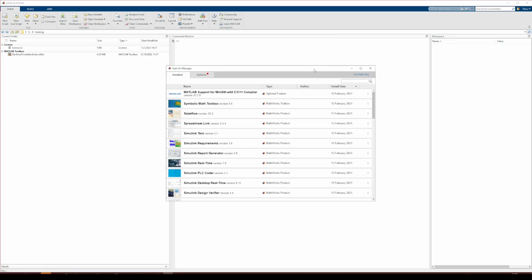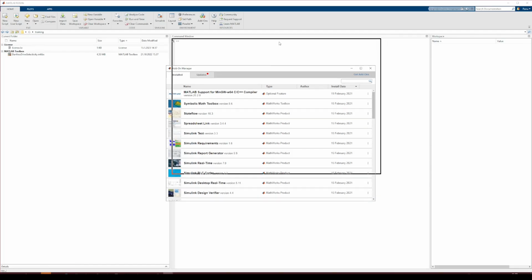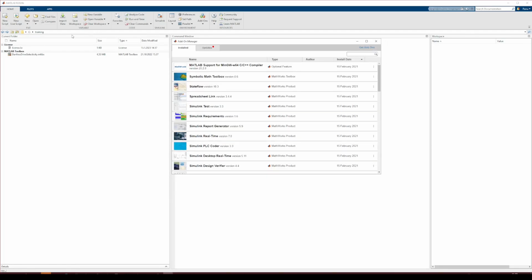If you want to carry out the uninstallation successfully, it is best to reboot MATLAB and then do the uninstallation to ensure that all the files and folders are removed successfully. And sometimes there may be a conflict if you have some files open from the installation folder, then MATLAB is not able to do the uninstallation successfully.